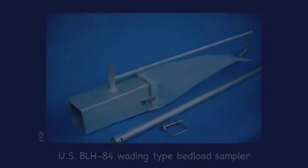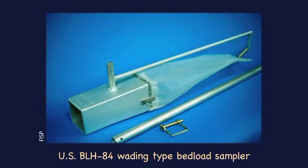There are two types of bedload samplers. 1. US BLH84 and 2. US BL84. The US BLH84 is a weighting type bedload sampler used to collect bedload samples from a stream that can be weighted. This sampler can collect bedload of particle sizes less than 38 millimeters at mean velocities up to 9.8 feet per second. The sampler weighs 10 pounds.